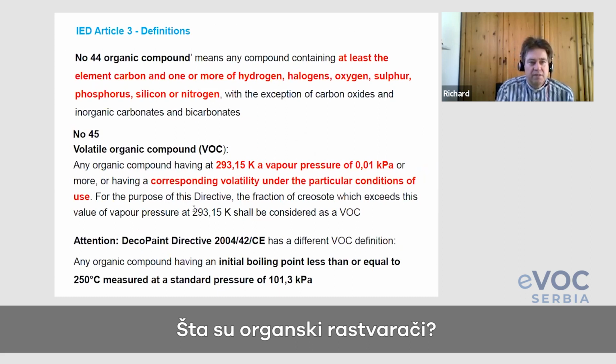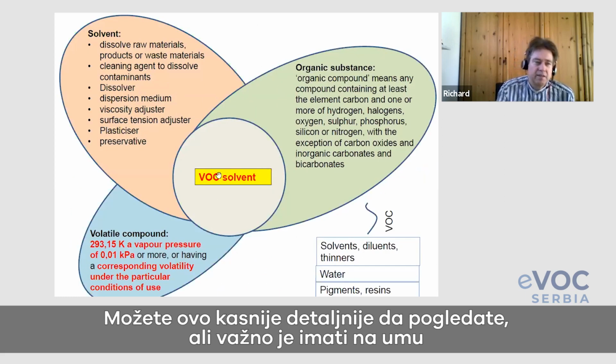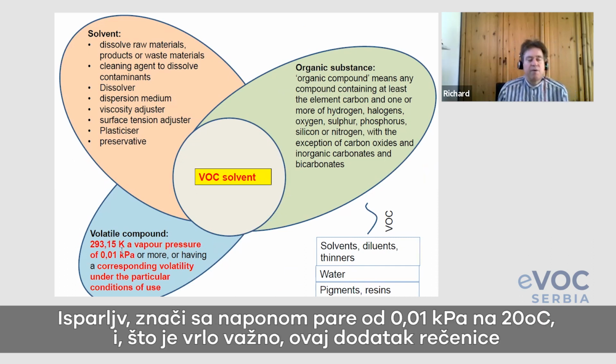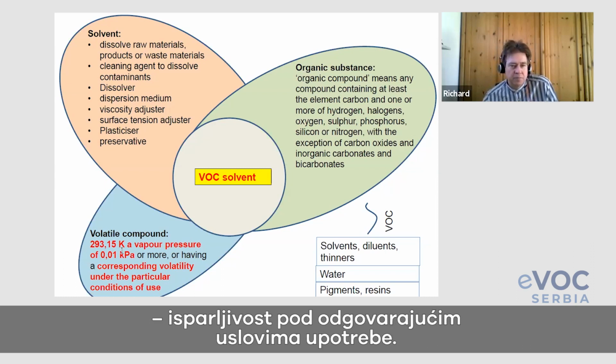Yes, organic solvents. Here you can look later at the more detailed information, but it's important to note it must be organic and it must be volatile. Volatile means it must have a vapor pressure of 0.01 kilopascal at 20 degrees Celsius. And very important is the addition of the sentence, volatility under the particular conditions of use.